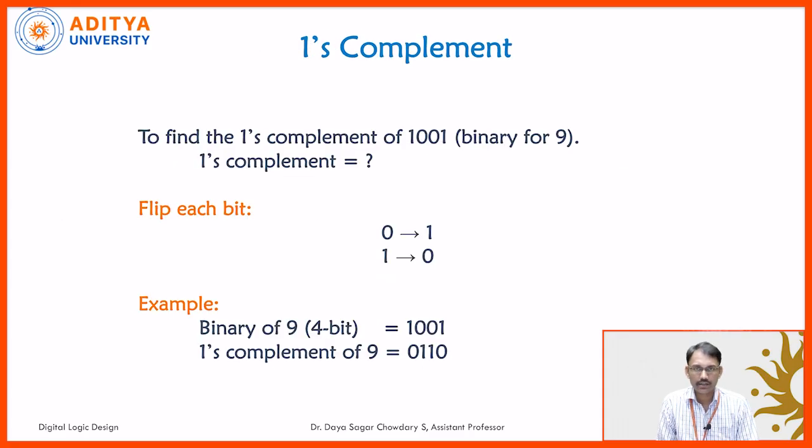So this is very simple binary addition. Why are we discussing addition in particular? For addition, with the help of the truth table, we can simply add two numbers. But coming to subtraction, computers and digital equipment do not perform the subtraction directly. For that reason, they operate on the second operand. We call these the first input and the second input. The first input is taken as it is, but the second input is taken as the complement of that particular number, and finally it is added to the first number.